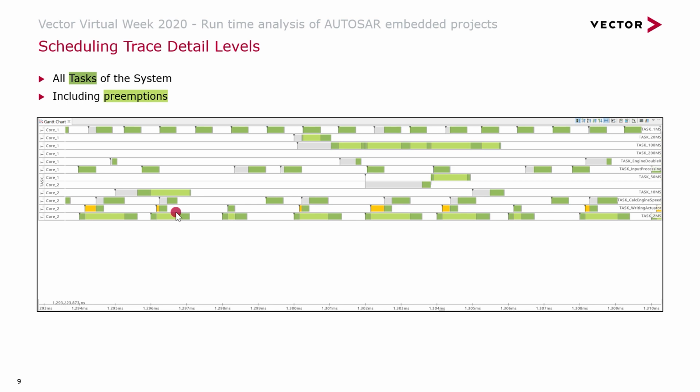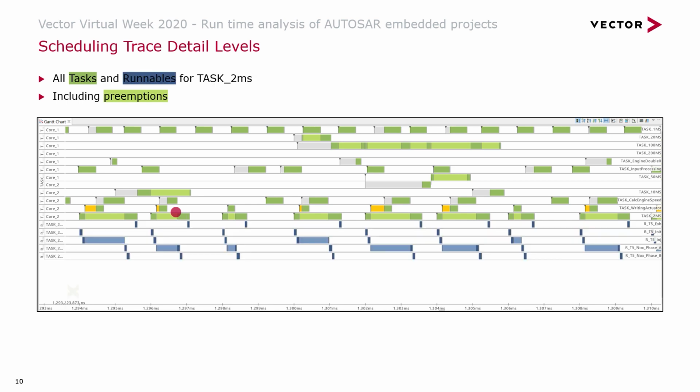And if I want to go a level deeper, and if I want to know which runnables within the individual tasks are running, they are displayed in blue in this picture, then via the hooks I also have the possibility to instrument the runnables so that I can also record the state transitions for those. And on the runnable level, I can realize which runnables are executed in which sequence within the task. And for the individual runnables, I can also define runtimes.